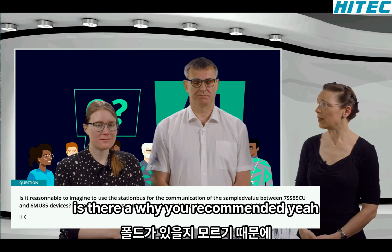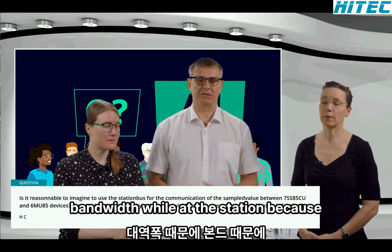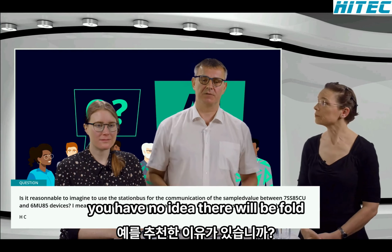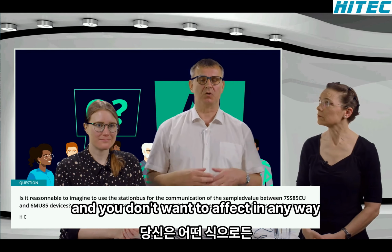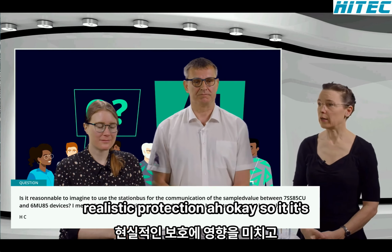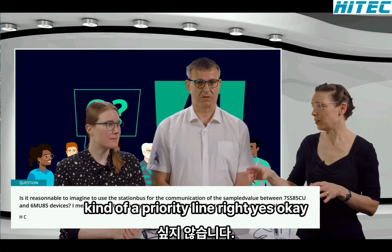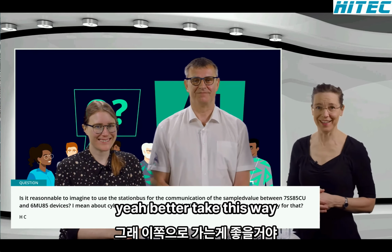Is there a why you recommend that? Yeah, because of the bandwidth. Via the station bus, you have no idea. There will be fault logs loaded, exhausting things, and you don't want to affect in any way really the protection. Okay, so it's kind of a priority line, right? Yes. Okay. Yeah, better take this way.